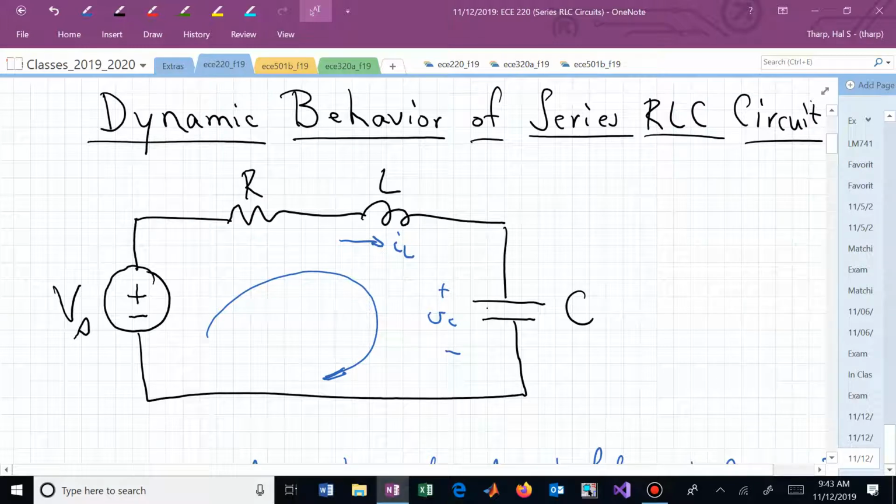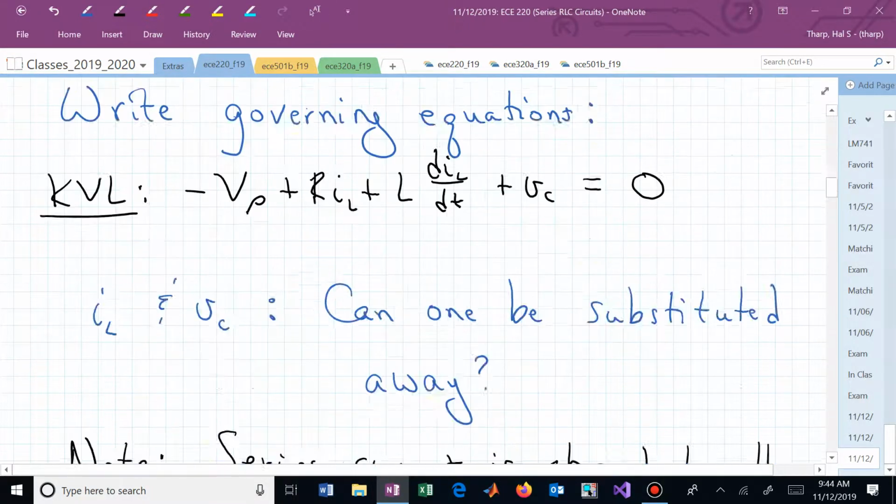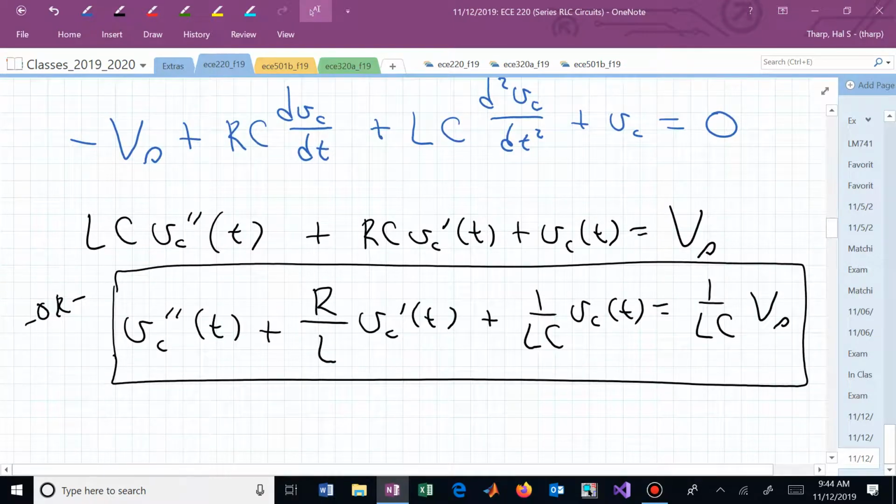Likewise with the inductor, you could have two inductors either in parallel or series, and you could create an effective inductor. But if it all boils down to this, that's what we're saying our second order differential equation is describing, is L effective, C effective, and R effective in this series mesh. That's what we now have used to end up with this second order differential equation.